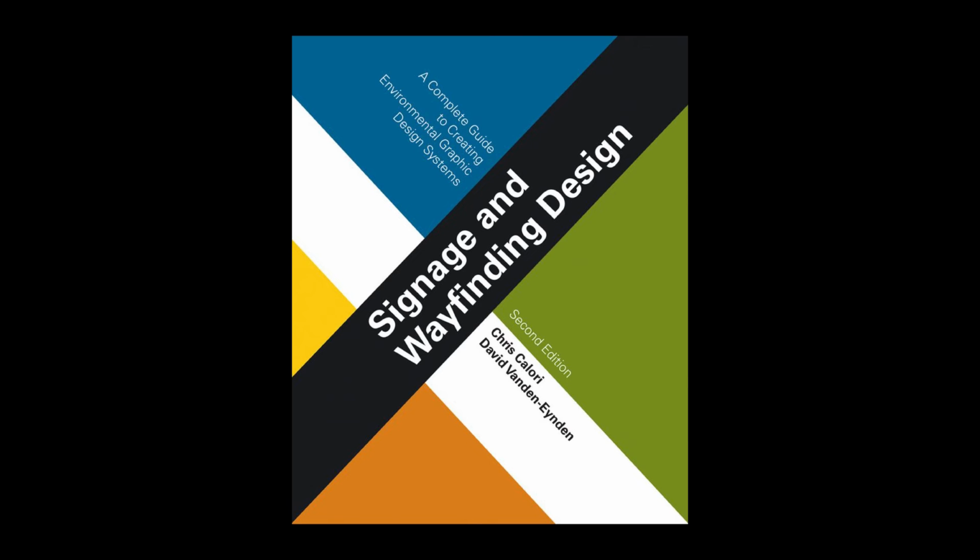Regarding sign mounting, lighter sign units such as wall plaques can be readily secured to mounting surfaces with just adhesives, typically double-sided foam tape, which is often used in conjunction with silicone gel adhesive. Adhesive mounting is often combined with mechanical fasteners, such as when a foam tape/silicone bond is augmented with mechanical fasteners for extra mounting support, a combination known as screw and glue.